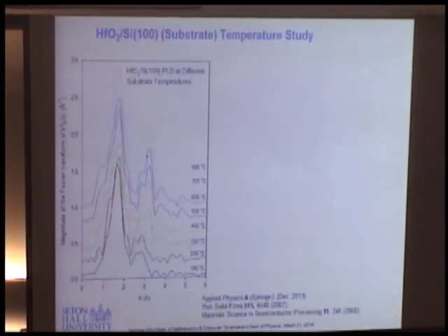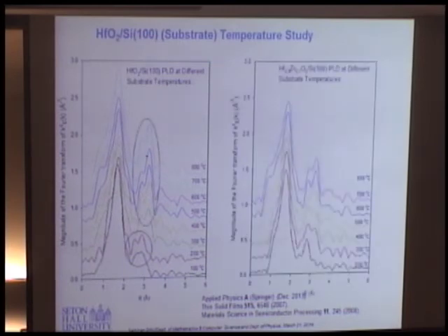Okay, then we didn't stop. We said, okay, let's try this experiment. I know that the zirconium was Intel's thing, all right? And we did in our laboratory, put some kind of zirconium into the films. Instead of just hafnium dioxide, you see that's the zirconium content, we just put a 0.1 molar ratio zirconium, okay? What happens when you put the zirconium, you delay this transition.